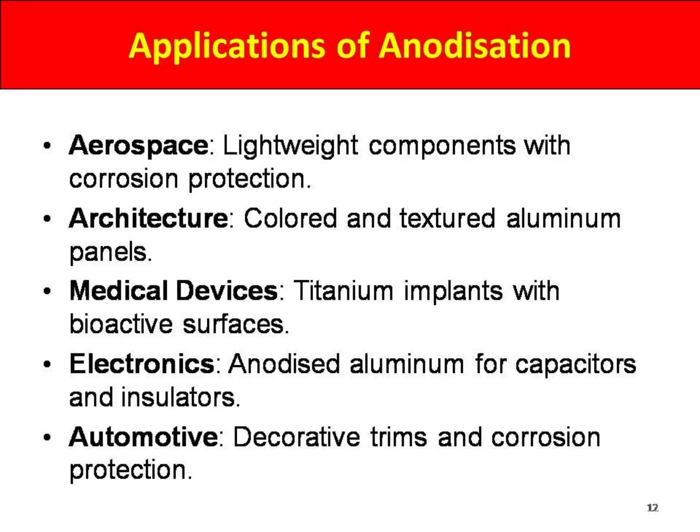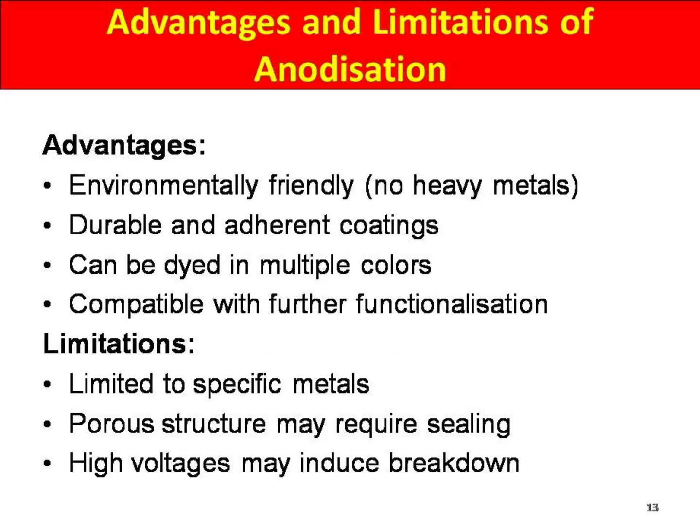The anodization process is applicable to aerospace, architecture, medical devices, electronics and automotive industries. The advantages are: environmentally friendly, no heavy metals involved, durable and adherent coating, can be dyed in multiple colors, and compatible with further functionalization.